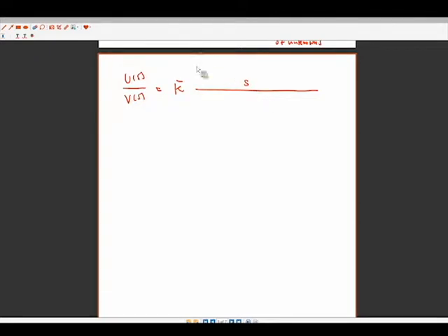And then we say we can decompose this into a set of real poles: s over tau 1 plus 1, s over tau 2 plus 1, s over tau 3 plus 1. It doesn't really matter what these values are, but they are all not equivalent to each other. We don't have any repeated poles. We just have some sort of ordering of these. So our transfer function, even though it has all these complicated coefficients, which we're not going to go into in this example, is something, and we want to understand what is the general shape of this Bode plot?